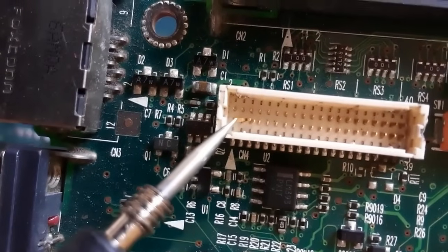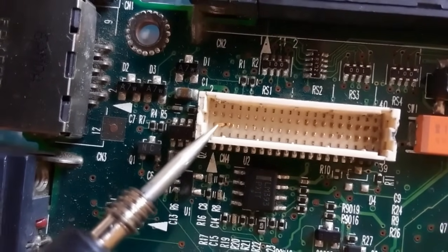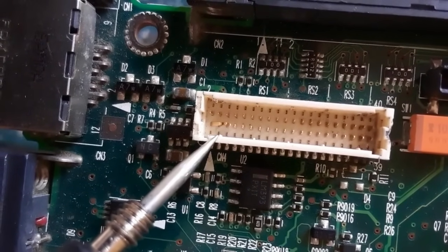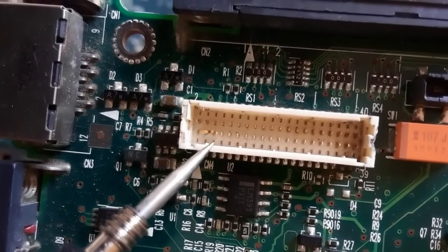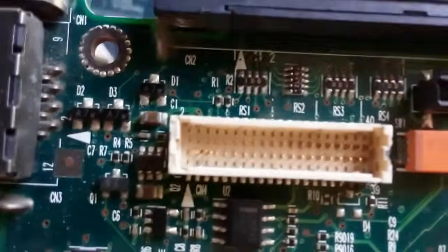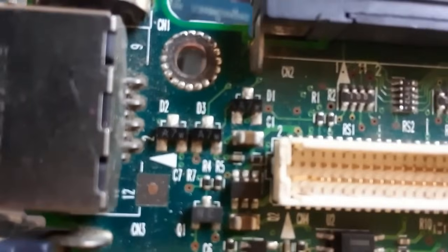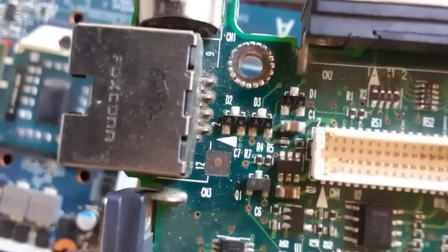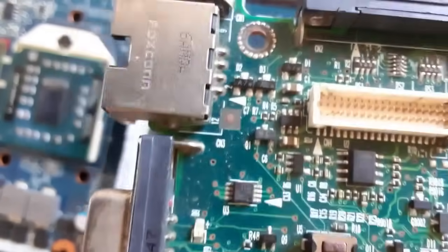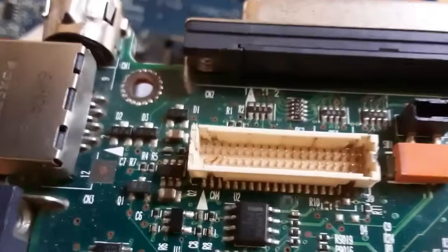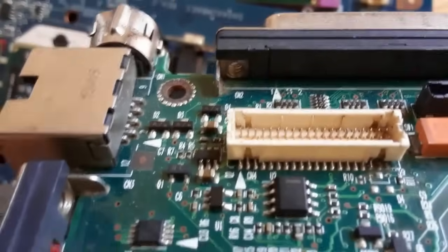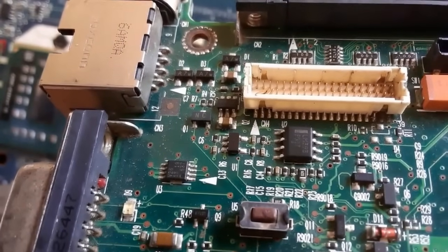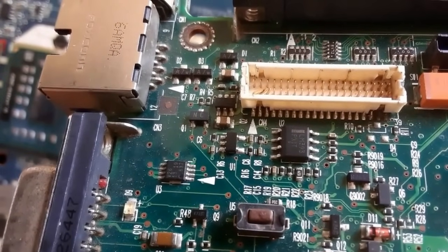As you can see, these bended pins touch each other, so we can get here a short circuit, especially when the 2 pins that touch each other are ground and plus 5 volt, for example, or plus 3 volt, etc. Okay, so you should always pay attention. I get many motherboards with this kind of problem. As you can see here in the image, bended pins in this connector.